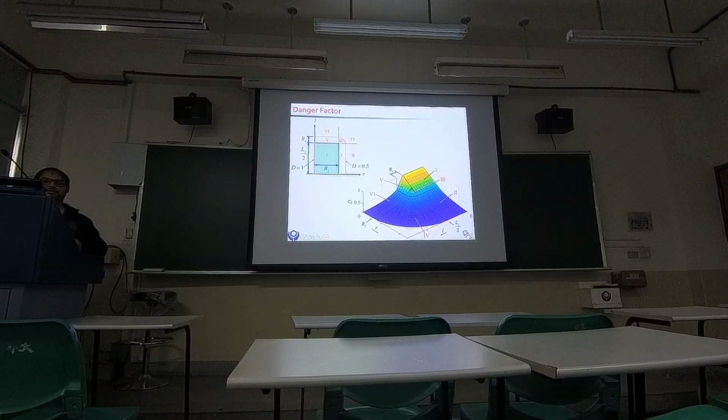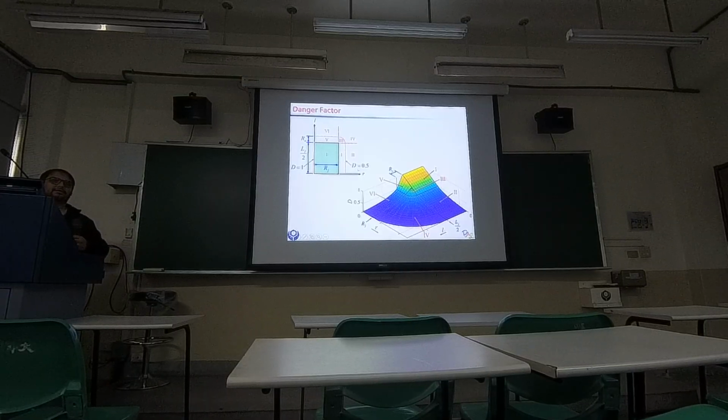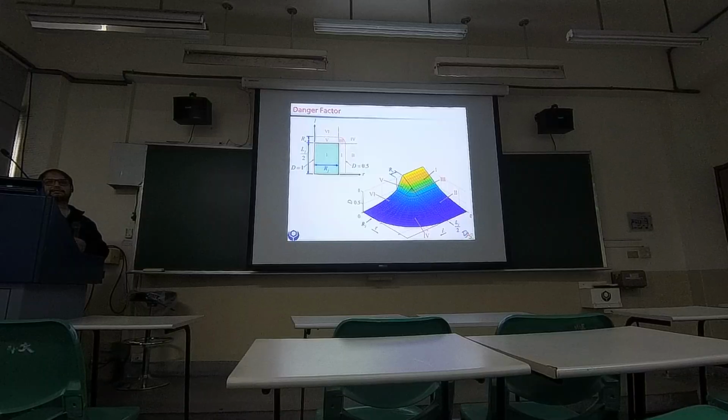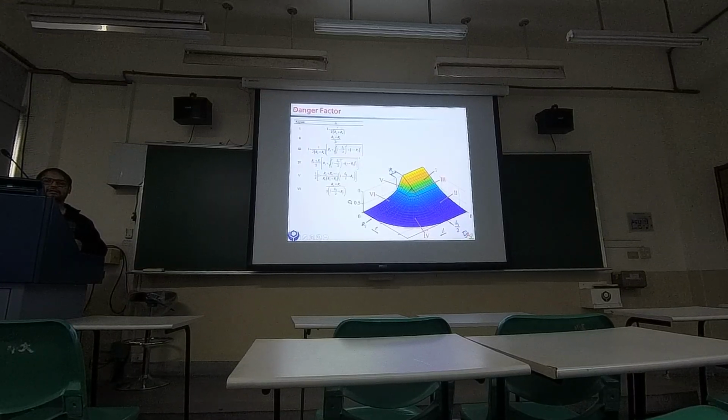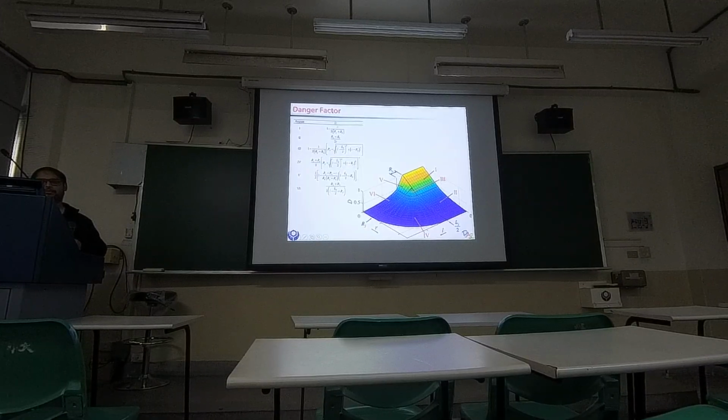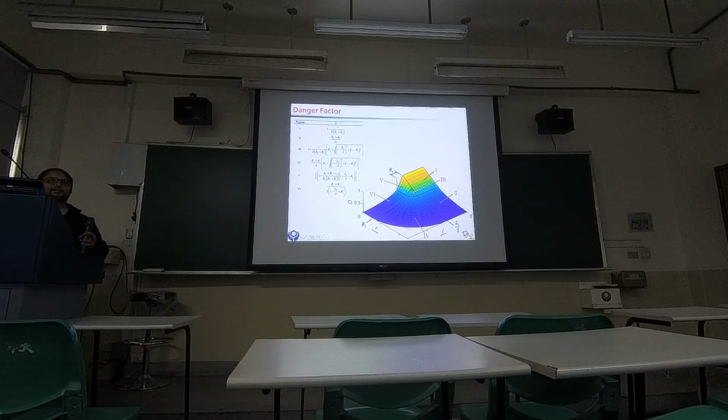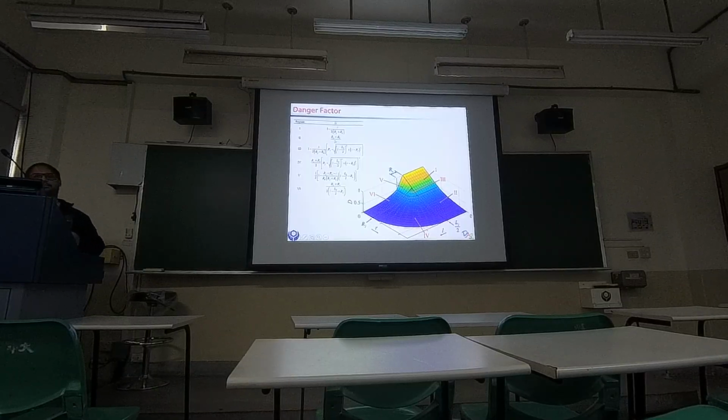Observe that we have made a boundary where the danger factor is 0.5, which is when the body is just colliding with the obstacle. All these regions have equations developed using the model of a sphere as an obstacle and a joint as a cylinder.